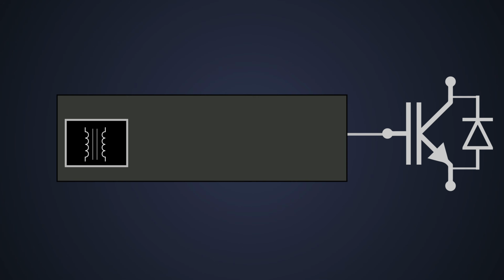If a driver has transformer-based isolation barriers, then they are particularly robust with substantial voltage ratings, which go in the range of 1 to 5 kV AC.